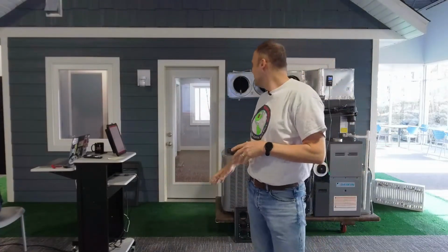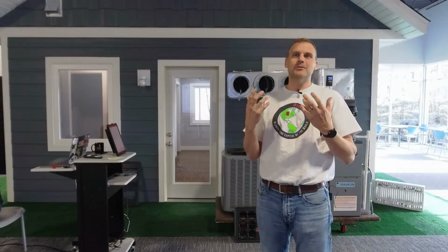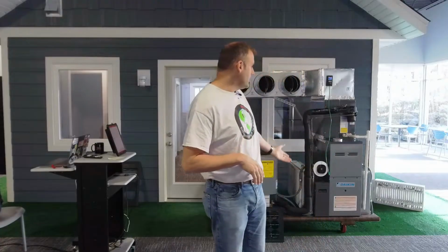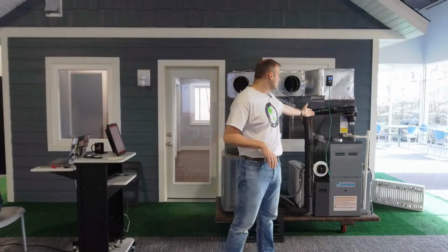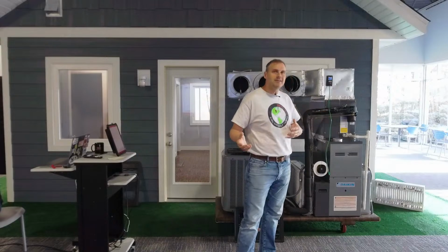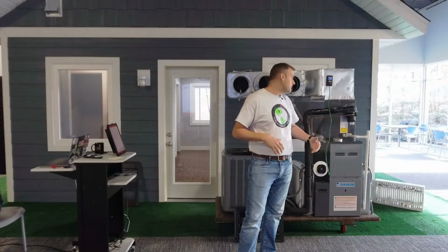So we've got a system behind me. We're going to run it, and what I want to know is total system airflow. Why do I want to know total system airflow? Well, if I was running it in cooling mode, I'd want a specific amount of moisture removal, latent capacity, out of that coil, and I'd want a specific sensible capacity out of that coil, right?